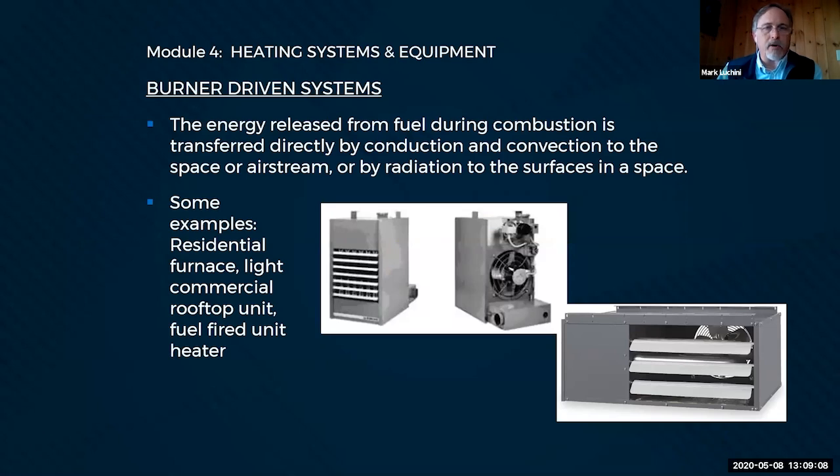We also have fuel-fired unit heaters that we use. A couple different models here. These have the vertical burner sections in them, whereas if you're tight for space, you can go with a low boy unit. They tend to be a little bit more expensive, burner technology. It's a horizontal drum and tube burner inside, but they're both driven by propeller fans.